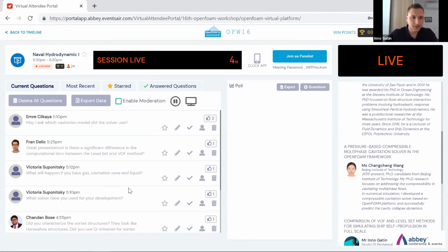So I have a question from Fran Delic. Great presentation. Is there a significant difference in the computational time between level set and VOF method? That's an interesting question. Well, time step to time step, not really, but we have found that level set takes a bit more to converge the wave field.